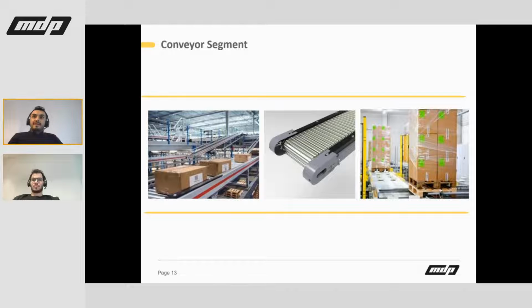You can also define capacity limits, which are quite important when it comes to conveyor segments. So this can be the number of HUs that can be placed on a certain conveyor segment, or this can be the weight or volume of a certain HU type that can be used at a certain conveyor segment, etc. And the PLC, by using scanners, can decide on which conveyor segment the HU is going to be transmitted next by checking capacity limits and additional properties if defined in the system.